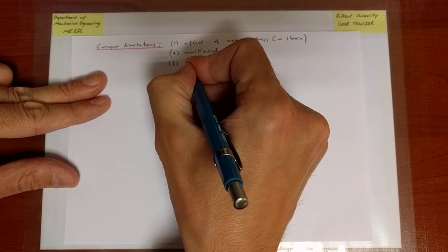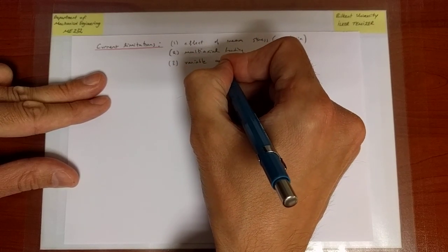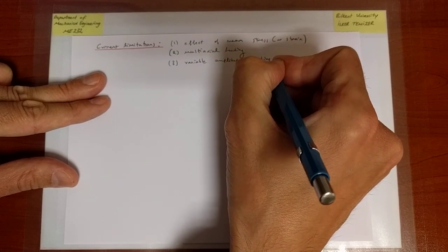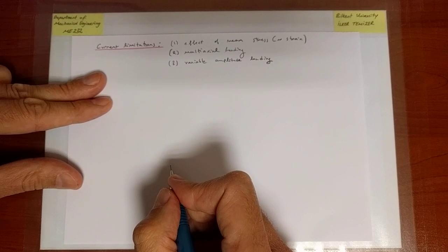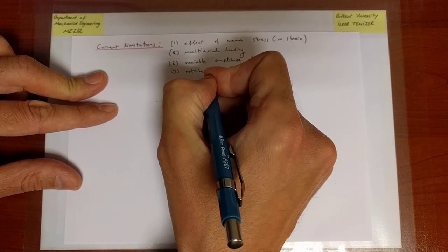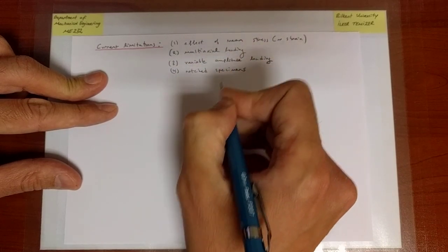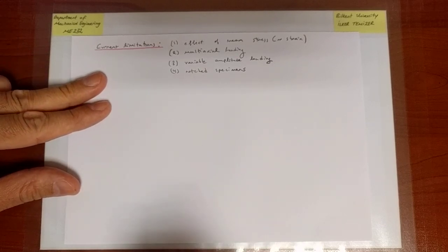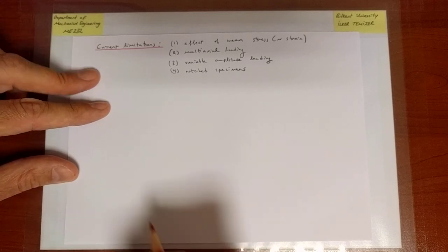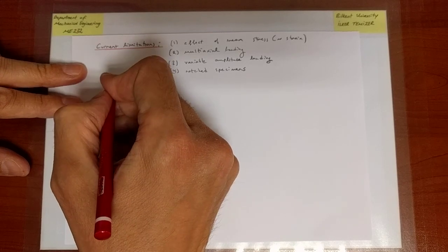Three, we assume that the amplitude of the strain does not change. In general, we can have variable amplitude loading, which certainly needs to be also addressed. And finally, and very, very importantly, we need to look at the effect of notches. So far we implicitly assume that there is no stress concentration. And in fact, this is exactly where the strength of strain-based fatigue lies.